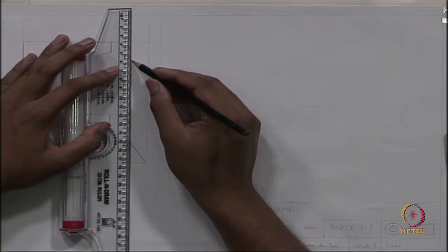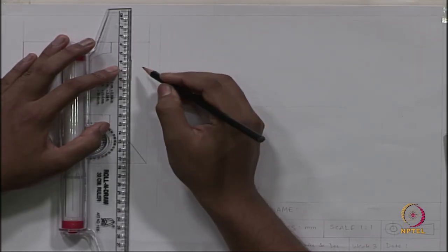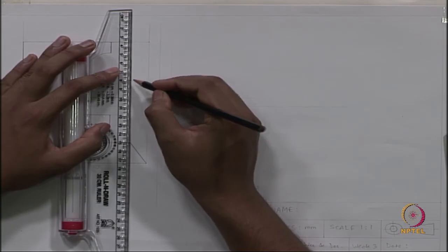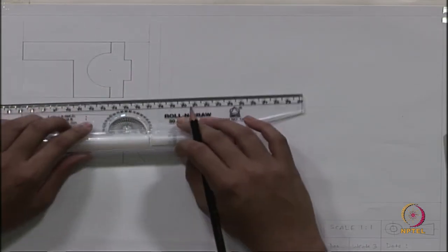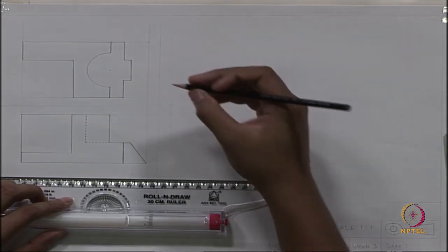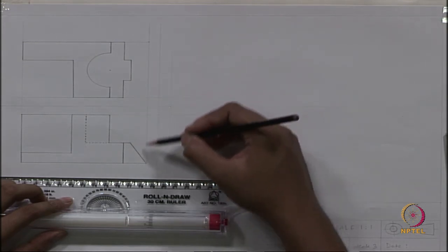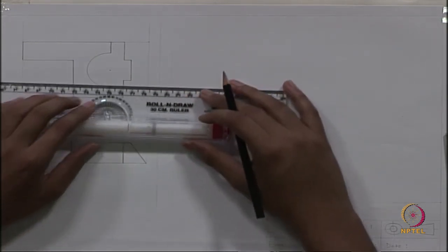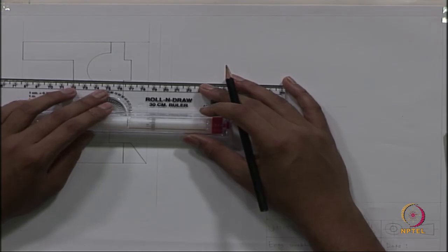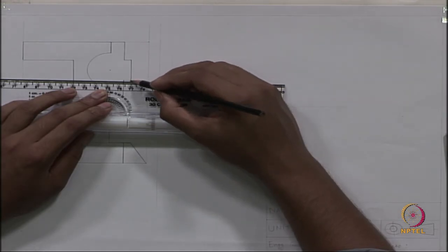This will be the first line of the inclined surface, which has a length of 24, you can check. And what will be the projected length of the inclined surface? That we will directly get from the construction line of the front view. We already know the construction of the front view, and from there we will just join these surfaces.